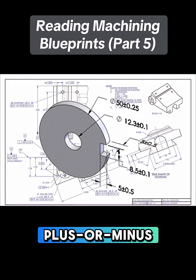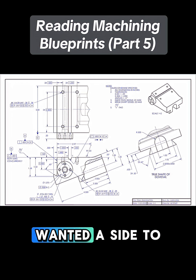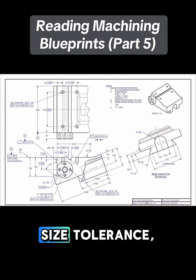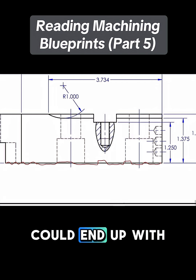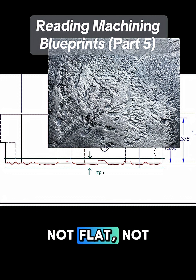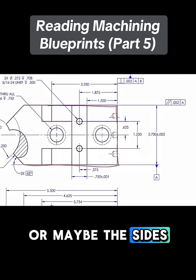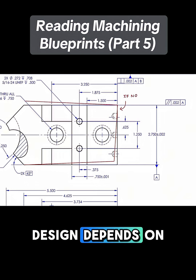But old school plus or minus tolerances just don't cut it anymore. Back in the day, if you wanted a side to be perfectly flat, your only option was to tighten the size tolerance, which made everything more expensive. If you didn't, you could end up with parts like this. Not flat, not square, and definitely not what you intended. Or maybe the sides aren't even parallel or perpendicular, even though your design depends on it. So yeah, without better control, things can go wrong fast.